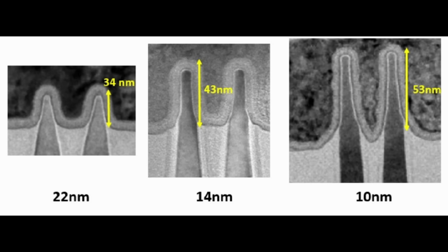In a FinFET, the height of the fin is pretty much proportional to the transistor's conductive strength. By increasing the height of the fin, the transistor can transport more current. So with the evolution of the FinFET, the transistor not only got smaller, as in they were more tightly packed, but also better at the same time.